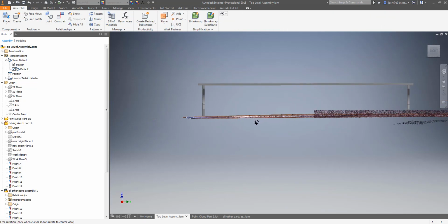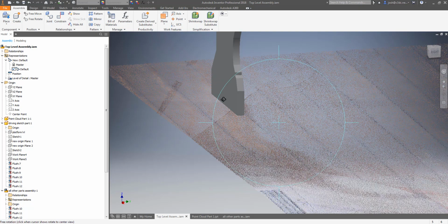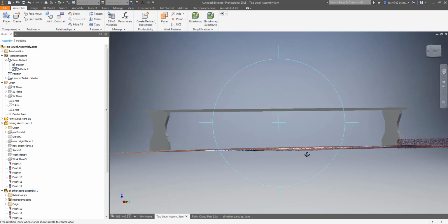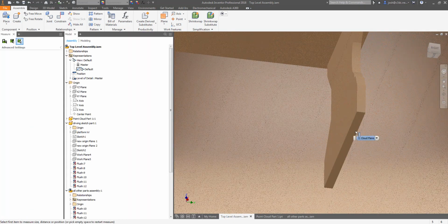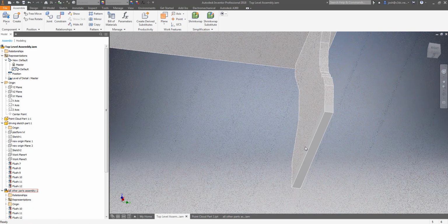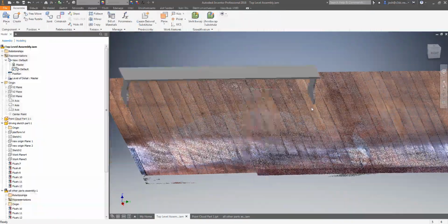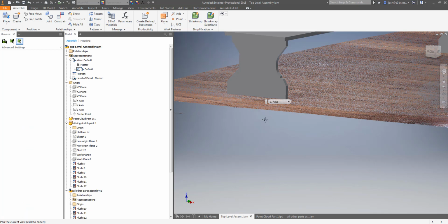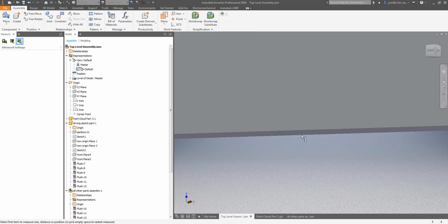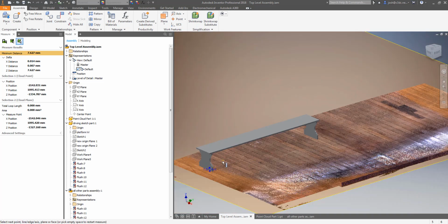As you can see here, there's a pretty big bow in the floor, so we'll need to work out how much of a bow it is and if that's going to be an issue. So we move the floor plane up so that one leg is on the floor proper, and measure the difference from the base of the foot to the point cloud. Here, you can see that it's only about 40mm of deflection in the floor. For what this is, I don't think that'll make a huge difference over the length of this seat, so we can leave it at that.